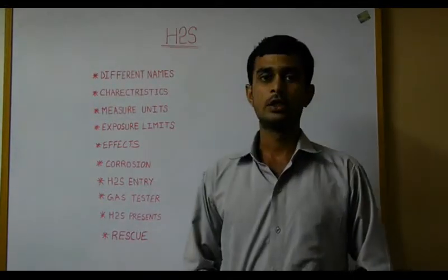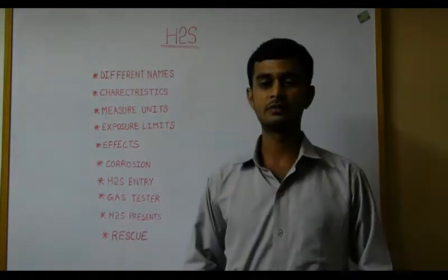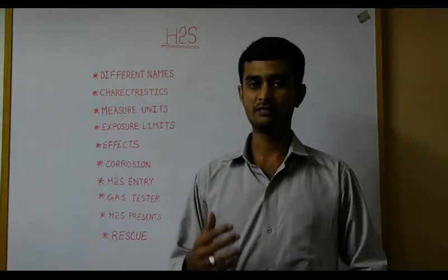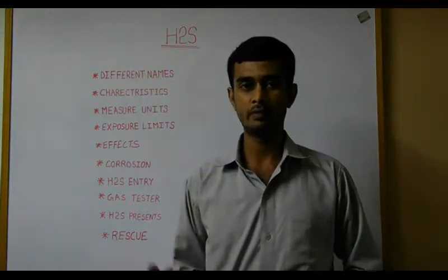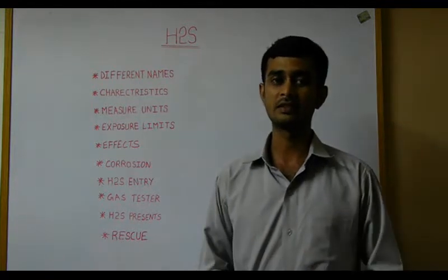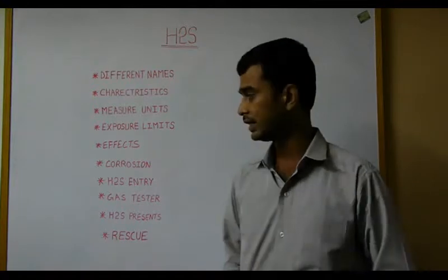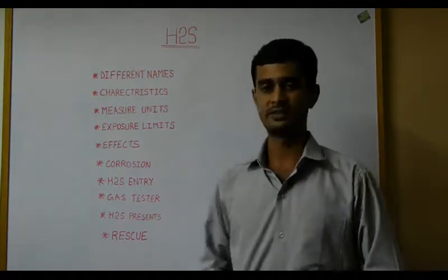H2S presence. In the presence of H2S, when your gas monitor alarms, you should not panic. Wear your life-saving apparatus or breathing apparatus. Try to evacuate immediately. In some cases, as engineering control measures, mechanical or forced ventilation is provided to reduce the exposure to H2S.